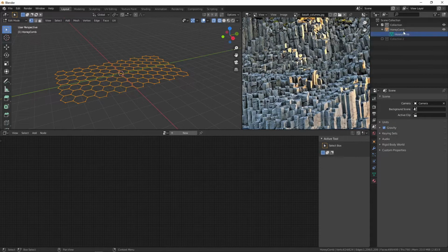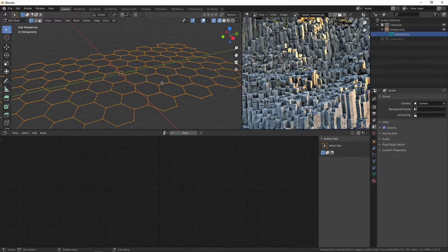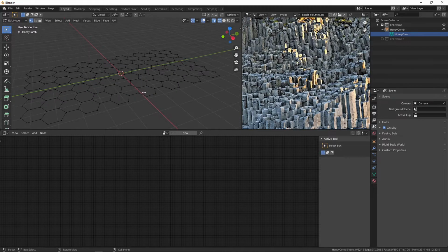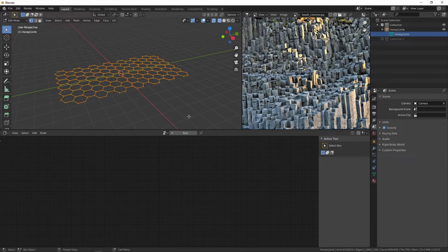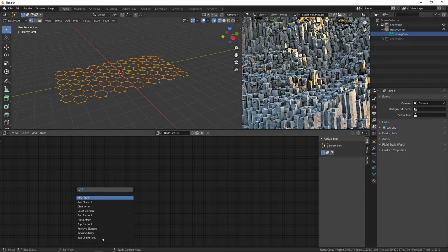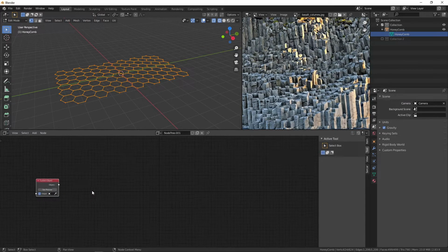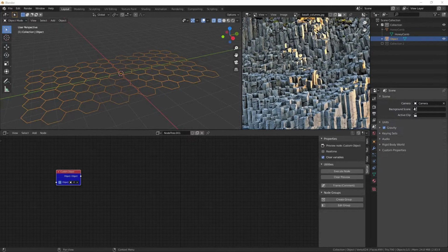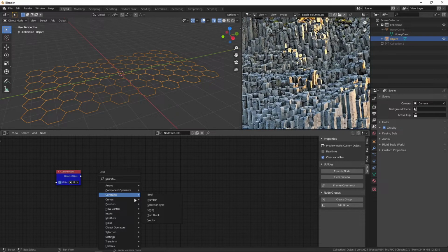So honeycomb is the name of the grid I'm starting with. It doesn't have any faces, at least not in the center. Take a look. So in Sorcar, we'll start a new graph and import a custom object. Here we'll just select honeycomb, set preview, and see it's created the object and it's hidden honeycomb by default. It's the standard behavior when you add a custom object. It just doesn't have faces yet, so I'll add them.